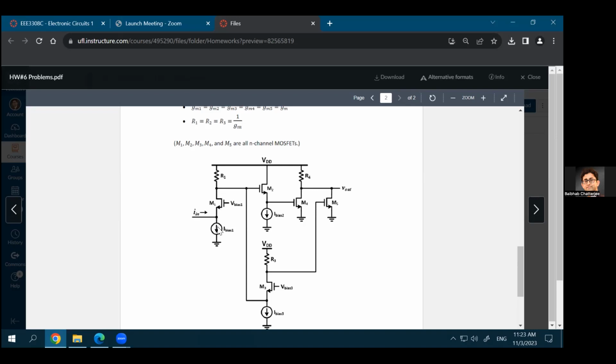And the resistance of a current source is how much? It's infinity. So looking down, you'll see infinite resistance. So all this input current is actually flowing through the transistor and going in the upward direction. No current will go in the downward direction. Even though you see a branching over here, no current will go down because the resistance looking down is infinite. The resistance of a current source is infinite. All of you hopefully know that, right?